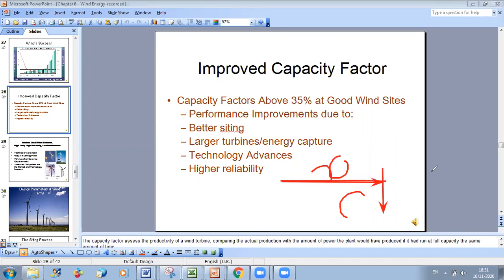And if you direct your blade appropriately, this will help lead to a better coefficient of performance. This is why they are talking about the setting. So it's true that the magnitude, as you said, does not directly affect the CP. But when you have high wind speeds, you can ensure a unidirectional flow that can hit your blade in an appropriate way without being resisted by the obstacles or air.